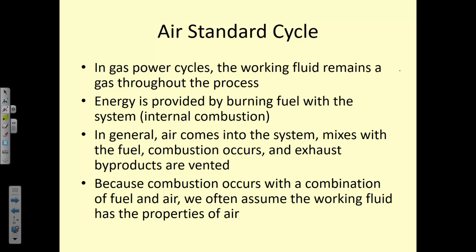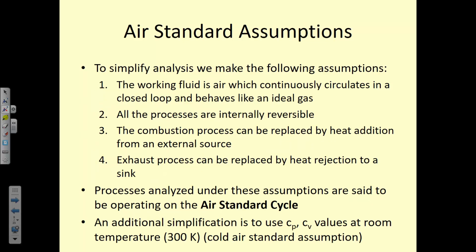So it's a simplification of this cycle, and any process that is operating under these conditions we call the air standard cycle. So we assume air is the working fluid, that it doesn't change state, that the combustion process is modeled by heat in, exhaust is modeled by heat out, and we don't need to worry about that.